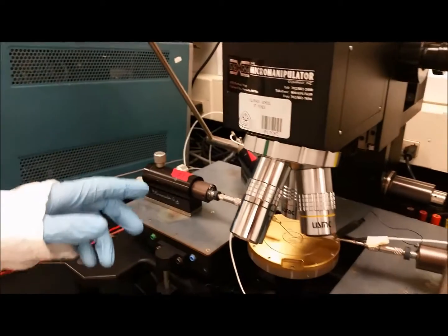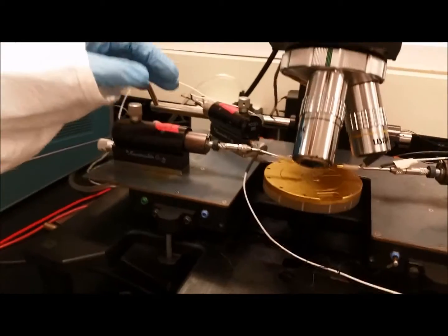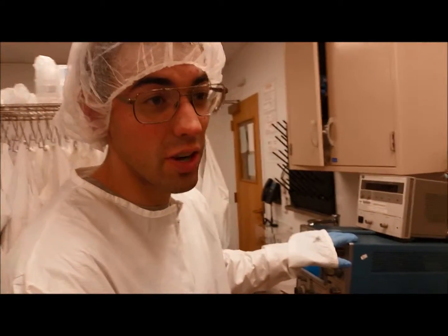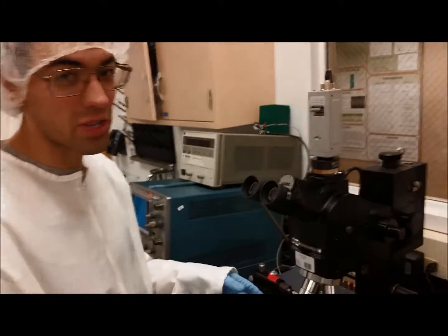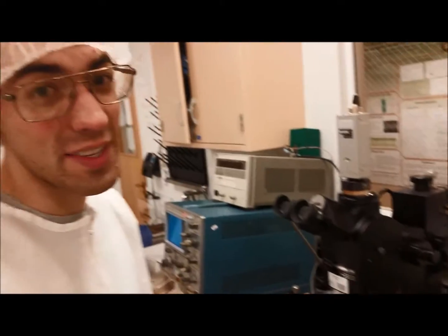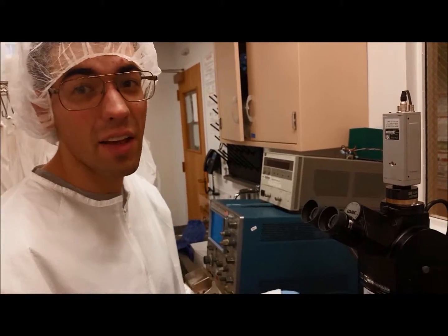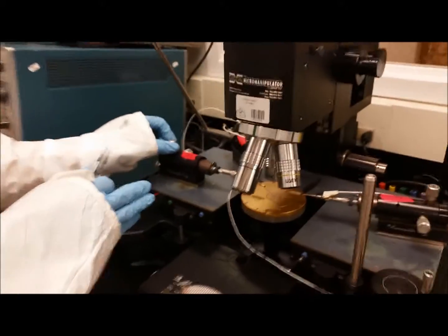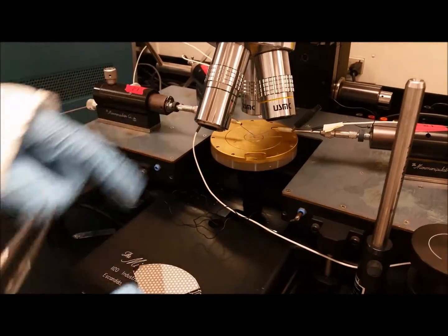Now, in general, for troubleshooting, you do not want to have pressed your probes too far into your device. This can scratch through a contact or an oxide, and if you have a bad trace on your curve tracer or your IV curve, it likely could be that, and it's worth checking. If you have scratched through a contact, there isn't really much you can do besides move to a different contact and remeasure, so hopefully you'll have another contact. But just as a rule of thumb, don't move your probes too far into the device, and always make sure you know where you're at.